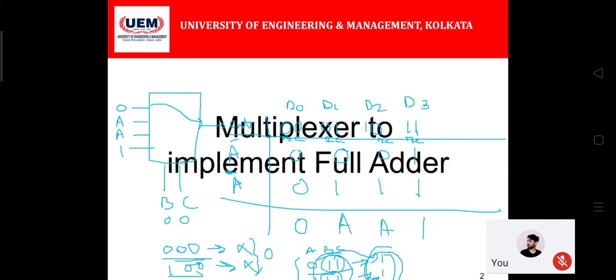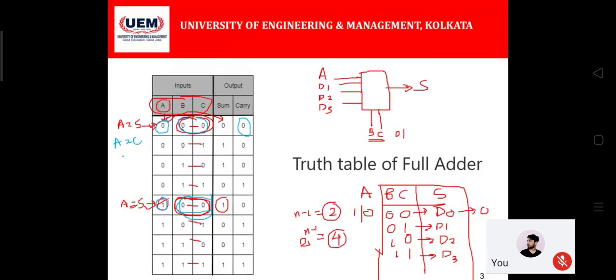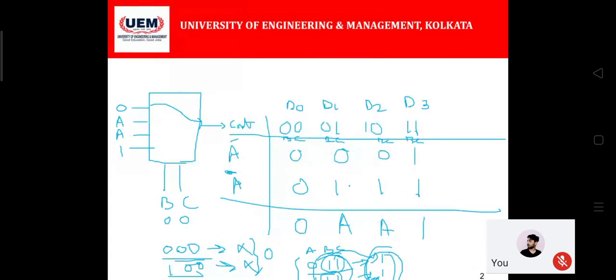So the truth table here, you can see this eighth term and the fourth term. To implement these two, I need to have an equation made like this, so that one must be provided, because it's not following a normal logical equation or a normal logical relation between A and the carry itself. Okay, so this way this 4:1 multiplexer becomes the carry out part of the full adder.